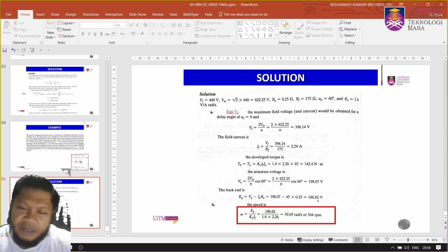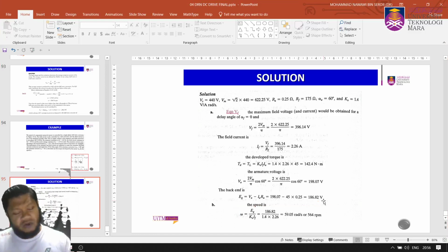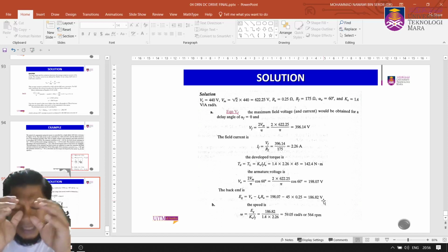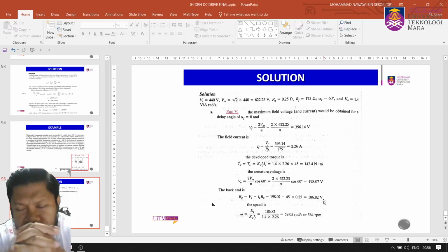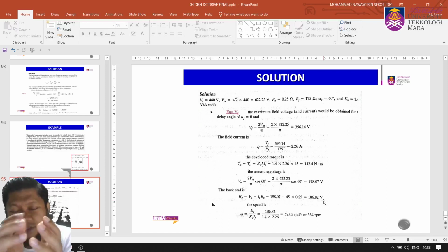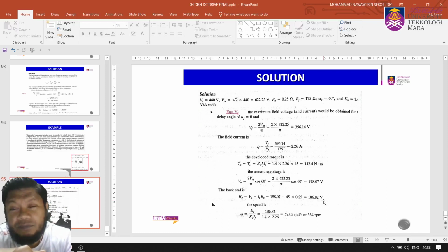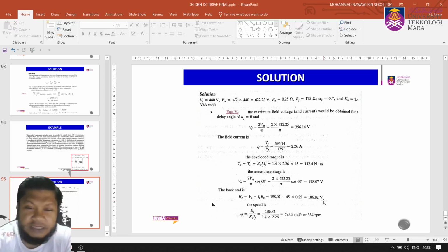Okay, that's very much what DC motor control is. We don't look into complicated circuits, just to give you a taste, to look into the basic DC drive control, by using the rectifier if the supply is AC, and you can have a DC-DC chopper circuit where the input is DC and you want to control your DC motor, right? So that's it.